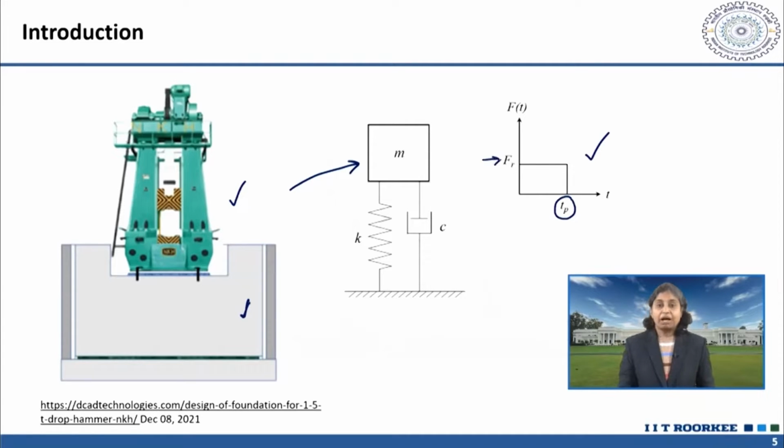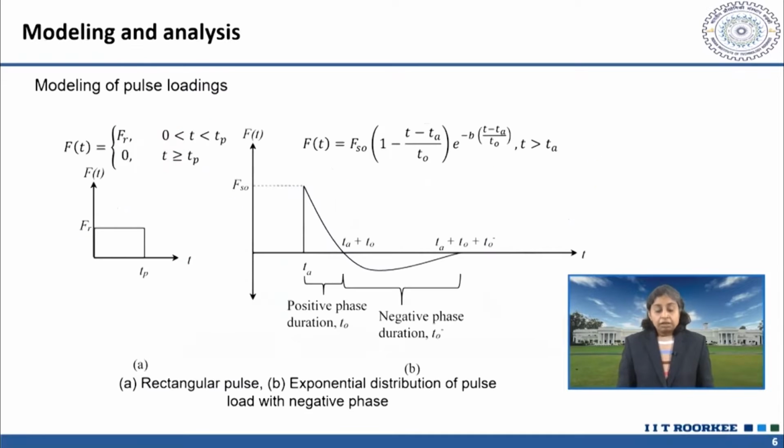the magnitude of the pulse is represented by Fr. Now, coming to the modeling and analysis part, first of all let us see how we model the pulse loadings. I mentioned to you that as far as the hammer foundation under its operating condition is concerned, we will have this kind of loading condition on that. Here again I am repeating that I am considering the rectangular pulse.